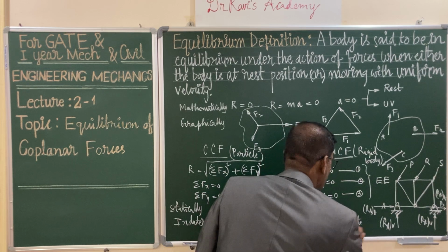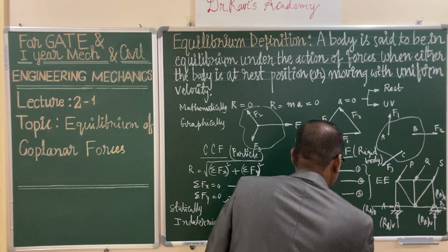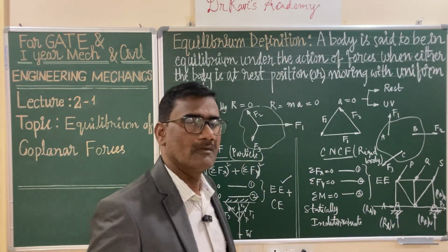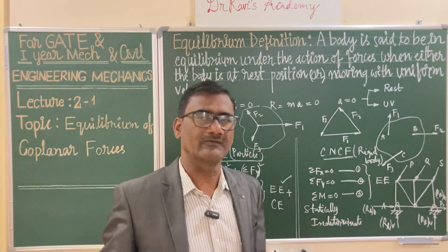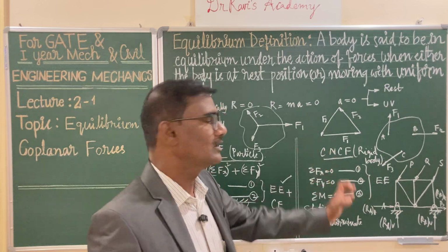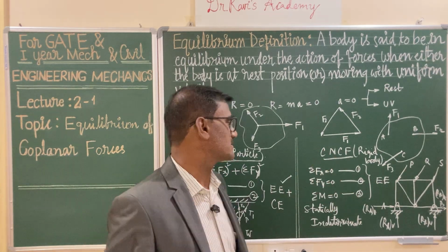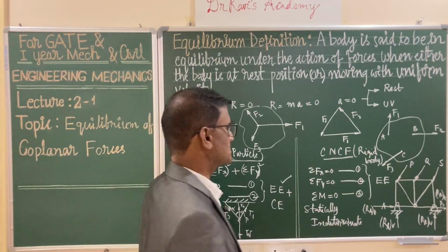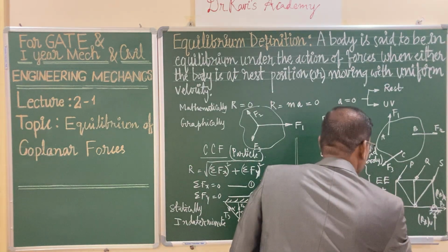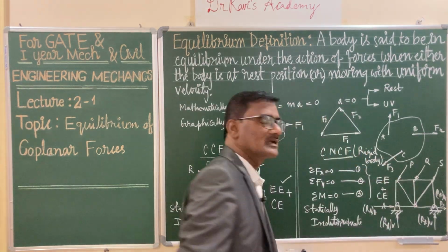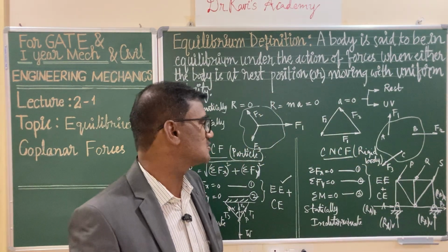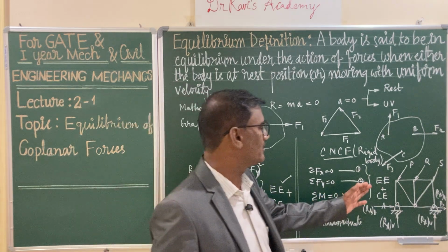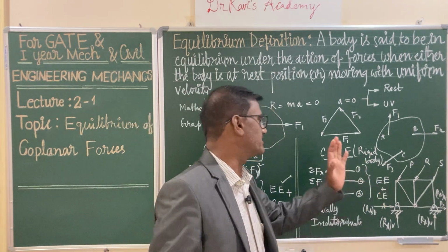So you are unable to solve these particular problems just by using equations of equilibrium. What is required is, again, the geometry of the deformations or compatibility equations. So equations of equilibrium plus compatibility equations. You are going to get the compatibility equations from the geometry of the deformation, and you will be able to solve this particular problem in strength of materials.